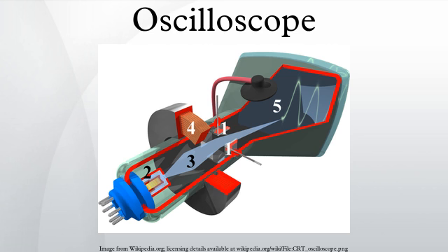Delayed trigger, which waits a specified time after an edge trigger before starting the sweep. As described under delayed sweeps, a trigger delay circuit extends this delay to a known and adjustable interval. In this way, the operator can examine a particular pulse in a long train of pulses. Some recent designs of oscilloscopes include more sophisticated triggering schemes. These are described toward the end of this article.